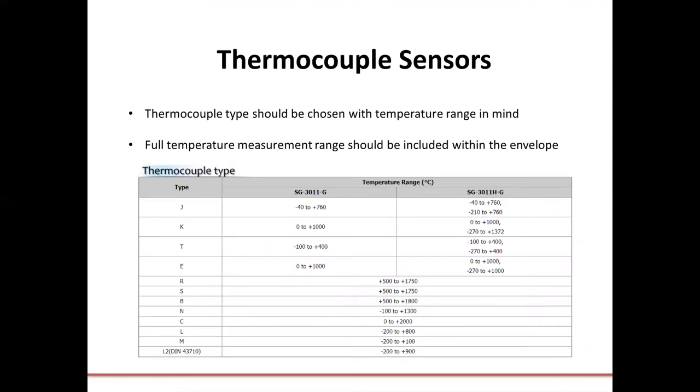The signal conditioner shown here can also be used if, for instance, you have 4 to 20 milliamp output sensors, but you have one temperature. So you only need one thermocouple, and therefore you can use one data acquisition module for everything, assuming that the signal conditioner will put out 4 to 20 milliamp, as opposed to buying a specialty module, which takes into account thermocouples as well. We'll go over some model selection shortly.